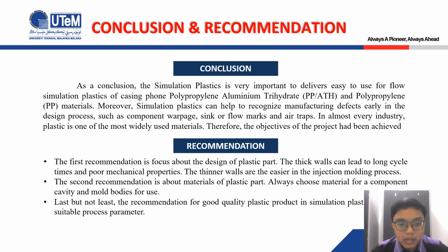For the recommendation, the first recommendation is to focus on the design of the plastic part. Thick walls can lead to long cycle time and poor mechanical properties. Thinner walls make the injection molding process easier. The second recommendation is about the material of the plastic part. Always choose the material suitable for the component, cavity, and mold bodies in use. Last but not least, for a good quality plastic product, the simulation plastic needs suitable process parameters.